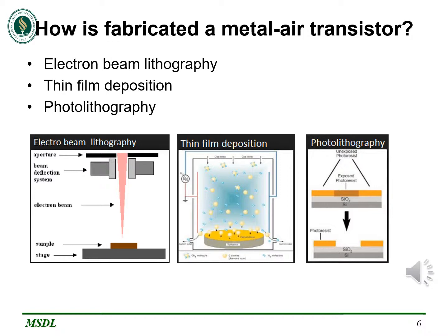Next, a 10 nanometer thick conductive layer of chromium was deposited by electron beam evaporation to avoid surface charging during electron beam lithography, to achieve maximum resolution. Subsequently, exposed patterns were developed in methyl isobutyl ketone mixed with isopropanol in a 1:3 volume ratio. The samples now had nanogaps defined. On this structure, a 50 nanometer thin metal film, tungsten, gold, or platinum for different sample sets, was deposited.